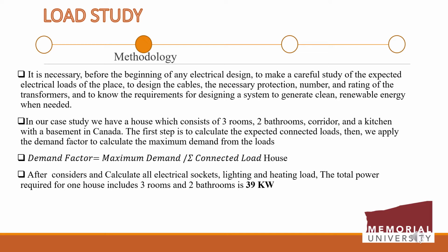Then we apply the demand factor to calculate the maximum demand from the loads. The demand factor is equal to maximum demand divided by connected load. After considering and calculating all electrical sockets, lighting, and heating loads, the total power required for one house including 3 rooms and 2 bathrooms is 39 kilowatt.